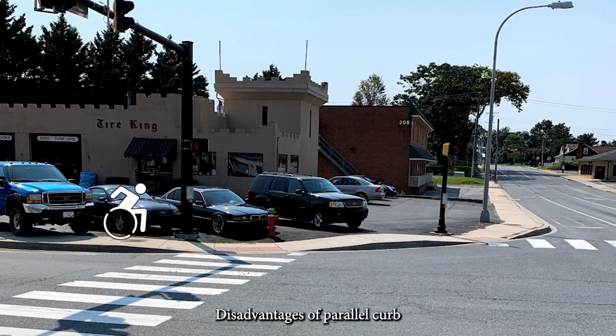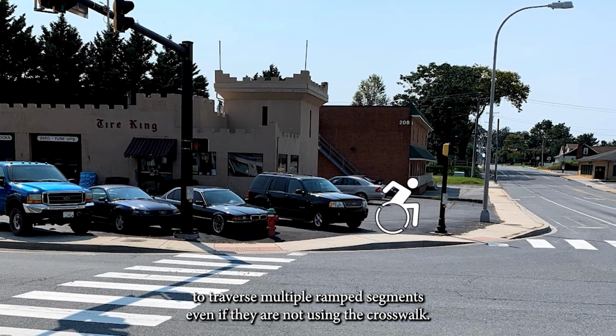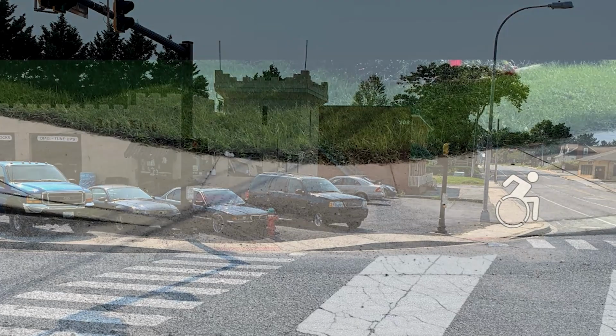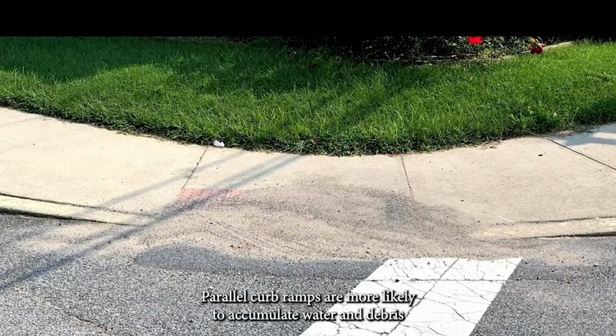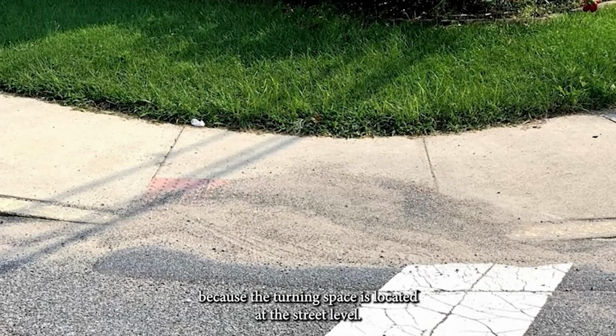Disadvantages of parallel curb ramps are that they require pedestrians using the sidewalk to traverse multiple ramp segments even if they are not using the crosswalk. And parallel curb ramps are more likely to accumulate water and debris because the turning space is located at the street level.